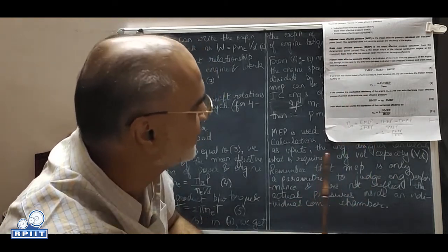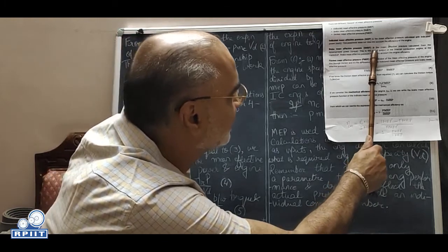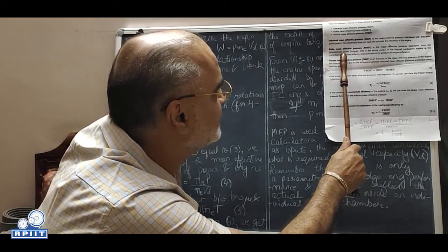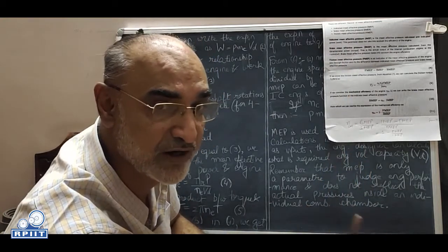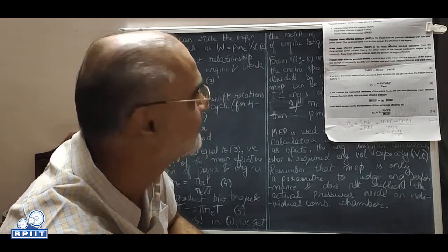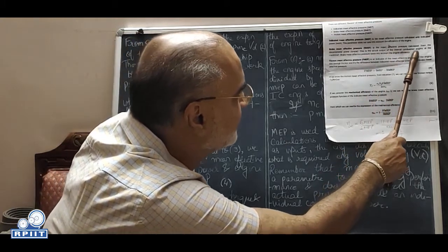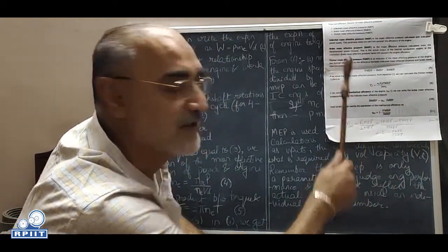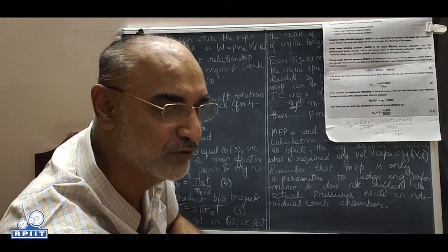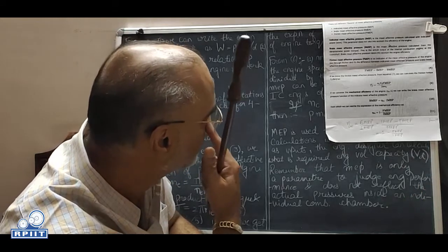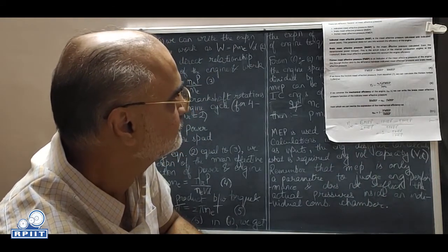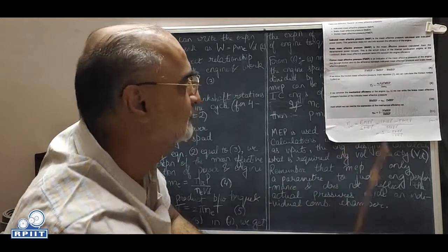Brake mean effective pressure takes into account the efficiency. The brake mean effective pressure is the mean effective pressure calculated from the dynamometer power or torque at the end of the crankshaft, which you can measure with a brake system. This is how it is calculated in the lab. This is the actual output of the internal combustion engine at the crankshaft, before the flywheel, before it goes into the clutch and gearbox. So brake mean effective pressure takes into account the engine efficiency. So this is just indicated, and this is the actual. Think of it that way.